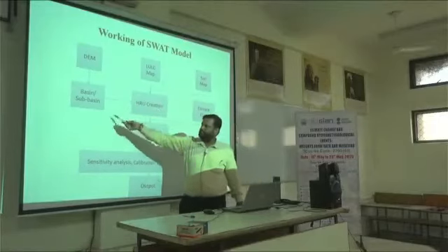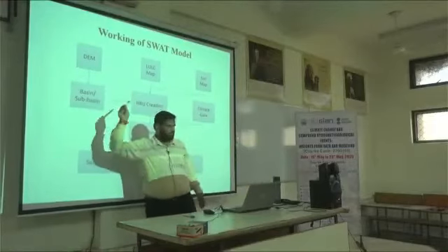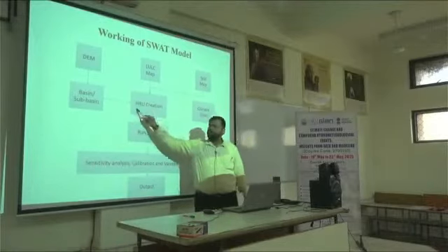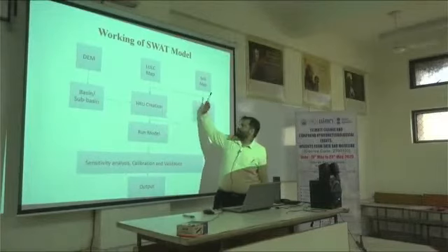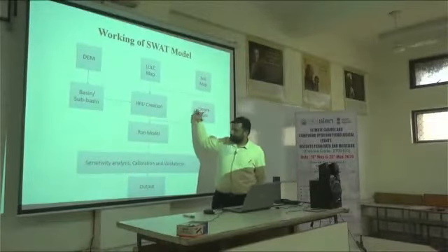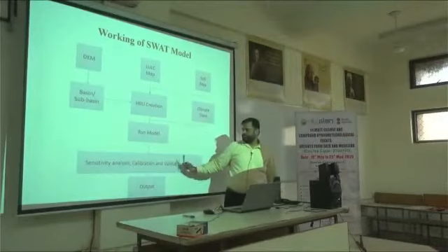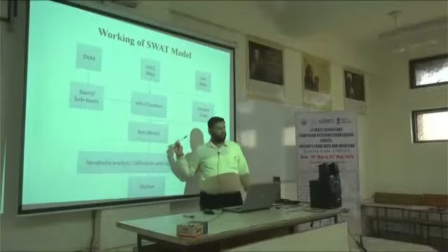The first step is to create the basin and sub-basin. Then the second step is to create the HRU. Then the third step is to run the model, and then we have to do the calibration and validation parts.